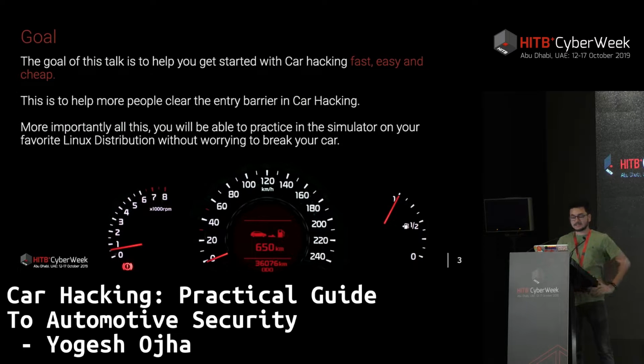I'll definitely help you get started with car hacking, in particular CAN bus exploitation. The goal here is to help you get started cheap, easy, and fast. Any tools that I'll be talking about here will be all free and open source. So even if you don't own a car, you can still practice car hacking and CAN bus exploitation freely using tools like ICSim, CAN utils, SocketCAN, and all this stuff.